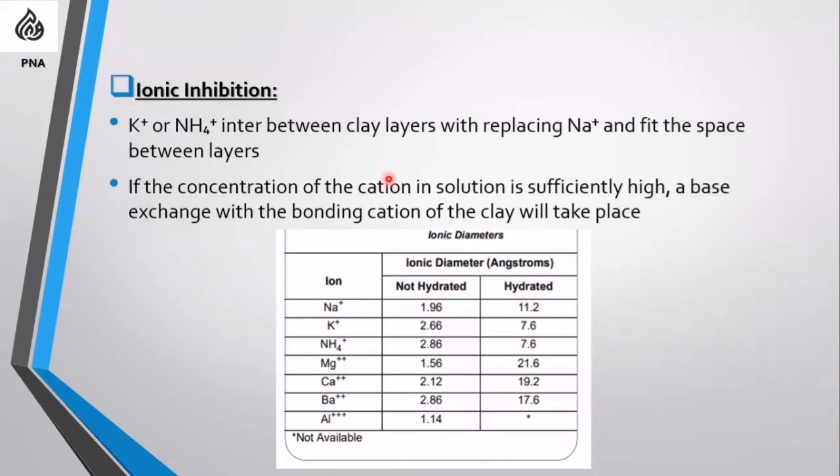When this clay finds some water, sodium is hydrophilic. It loves water. It absorbs too much water and hydrates to a bigger diameter, and this increases the distance between the layers, which is defined as clay swelling.